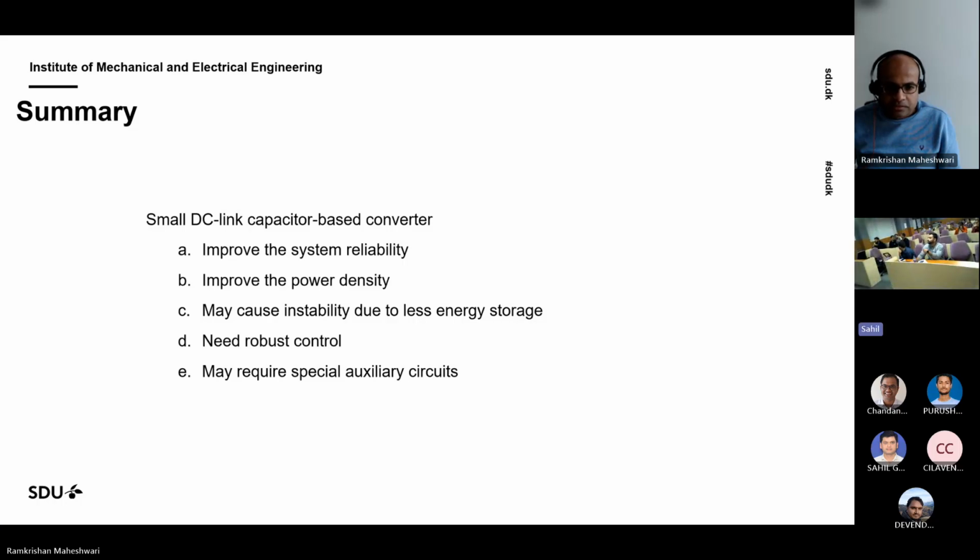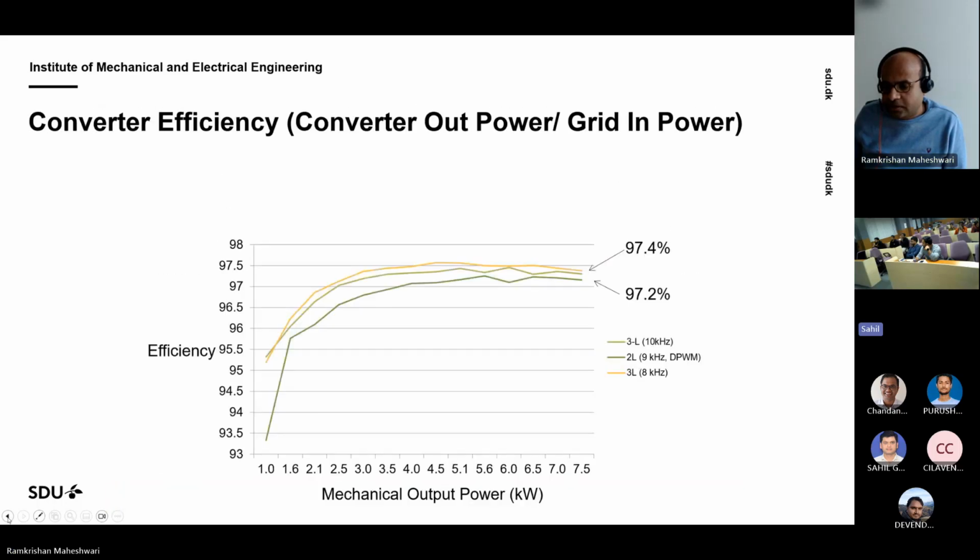Hello, sir. Am I audible? Yeah. Sir, my question is, since you were adding the DC ripple voltage to the VD and ID axis parameters, what is the effect of delay? Has the effect of delay been considered there? Because that will have another negative impedance. The sampling delay and PWM delays that will be there in the parameters. So the K will, instead of R, become some kind of a negative impedance.